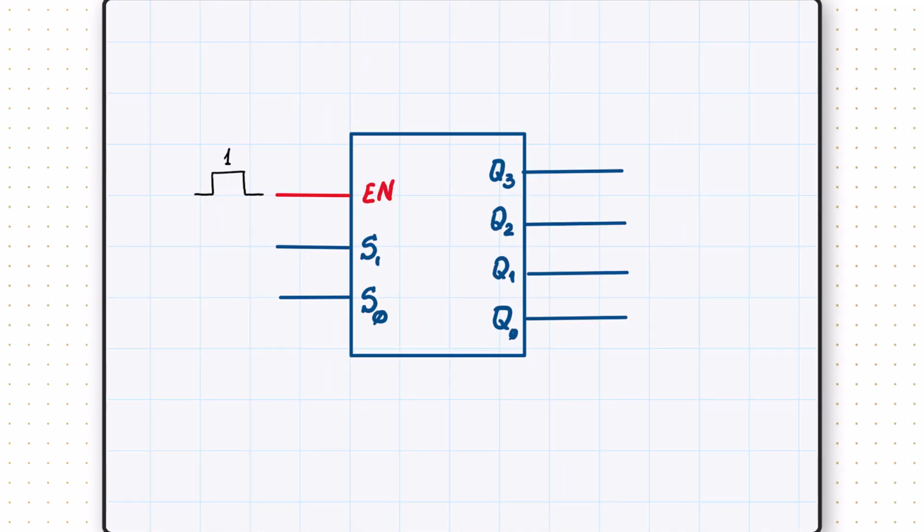The graphical presentation of the decoder clearly shows that we have the 2 inputs, the 4 outputs, and highlighted in red here is the enabling input signal with the value of 1. Because we're going to implement that decoder using an active enabling signal of 1, and we have to use respectively the AND gates, we can pull the expressions for the respective minterms as multiplication of the 2 input signals.